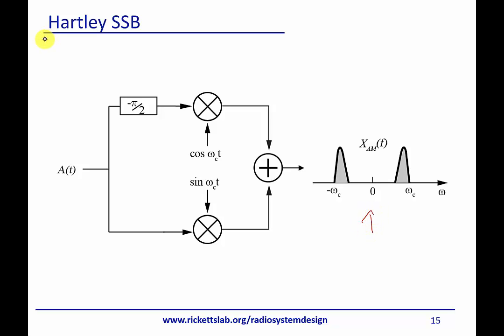And this is called a Hartley single sideband. It's a technique. And the challenge here is how do you do a perfect 90 degrees phase shift? Well, for a single tone, we can figure out what a 90-degree phase shift is in terms of a delay, and we could put a fixed delay in there. But that's a little bit hard to do when you have a wide spectrum, right? Because it's not like we're doing a single tone. We've actually got some bandwidth here. So it turns out that we can't do that exactly if we're doing it in simple circuits. We could, though, if we had a digital representation, we could shift each one digitally and then create a signal that effectively had this phase shift. And then we would just transmit this nice, beautiful signal just with a single sideband.